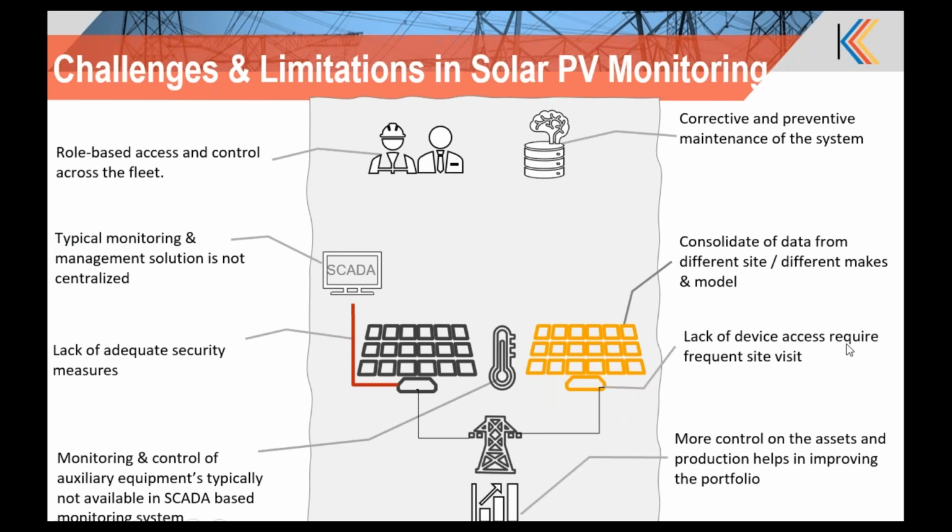For example, with the arrival of DER and smart inverters, you could control the volt-var and make the distribution grid stabilize and improve the power quality of the grid. So those kinds of var pumping can be done using the inverters by doing some remote settings.